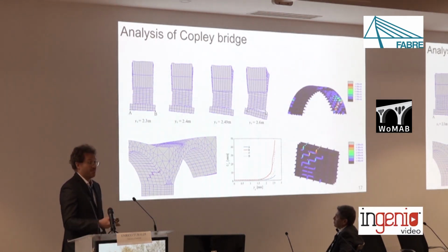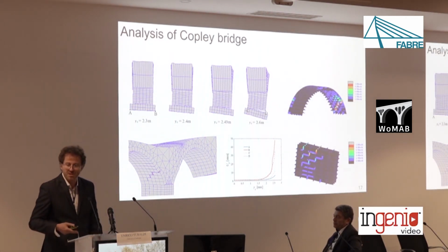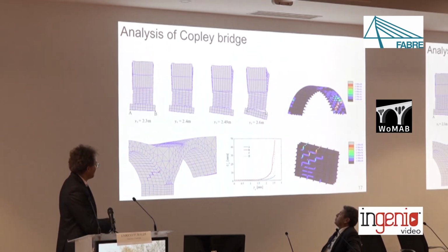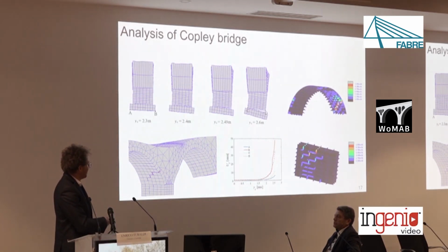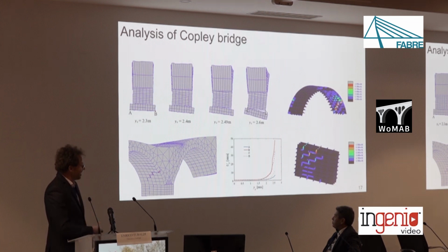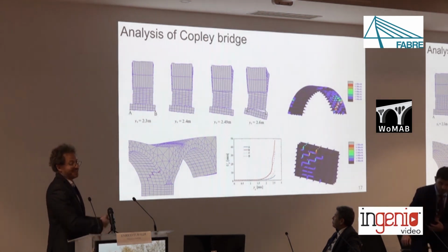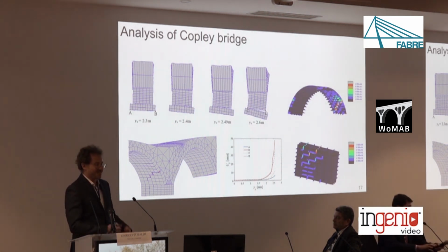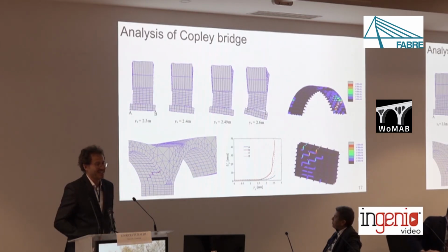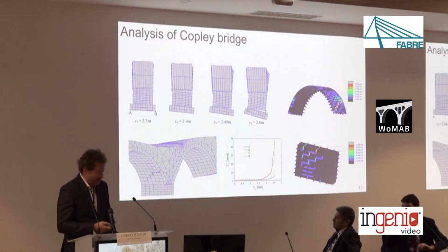And this has very important implication for monitoring of masonry arch bridges, because it shows you that masonry arch bridges don't exhibit any sign of warning of a critical situation until it's quite too late, and small increases of scour result in a very critical condition.